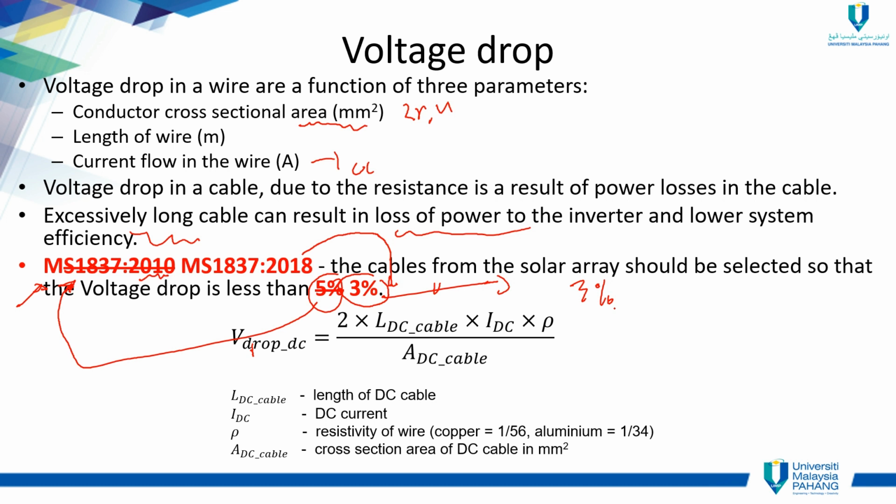What is the difference between this equation and the previous cable size one? Only this part, and it is extremely easy. It's the same case as before. Like I told you, if the total cable route is given, just put only one value, 30 meters only. The difference is only at the bottom part, where the size of the cable comes in. This is the size of the cable that you chose just now, for example, 2.5.